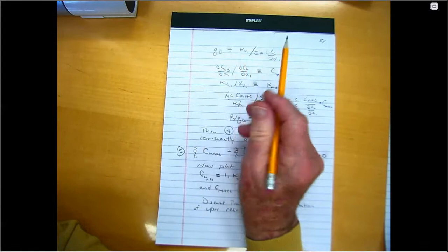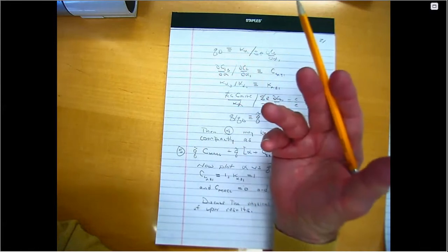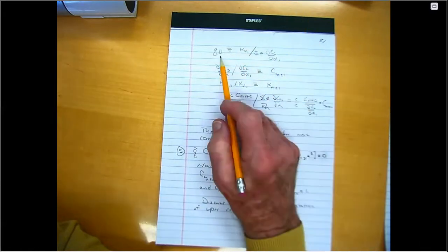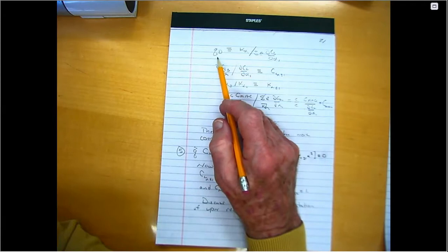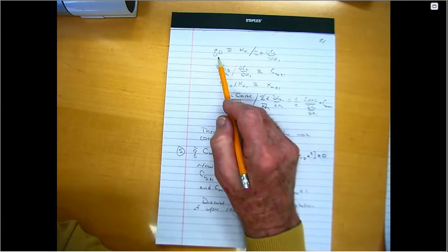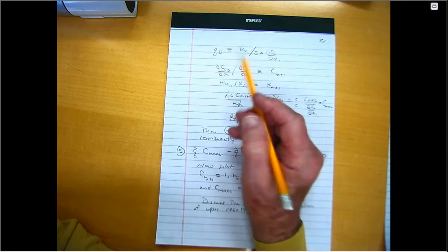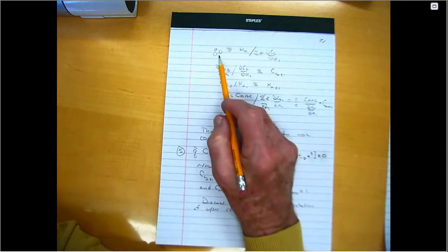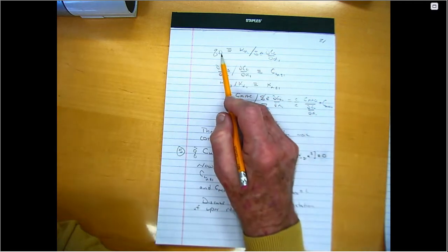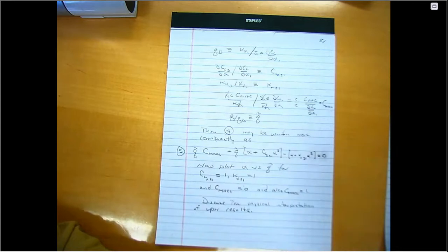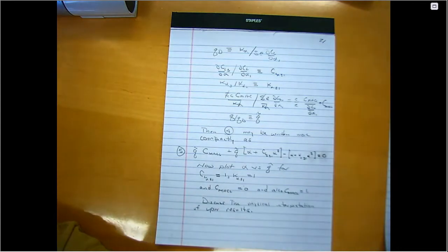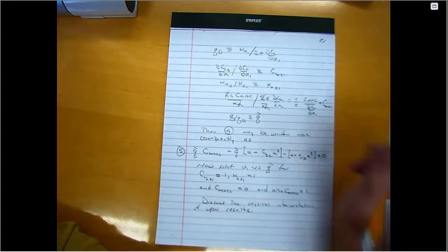You recall that we did a linear divergence analysis, right? And we identified the divergence dynamic pressure. So this is dimensional, right? I'm going to use this in the non-dimensionalized equations in an interesting and helpful way. This is the divergence dynamic pressure determined by the linear theory, where I don't include the nonlinear spring and I don't include the nonlinearity in the lift.